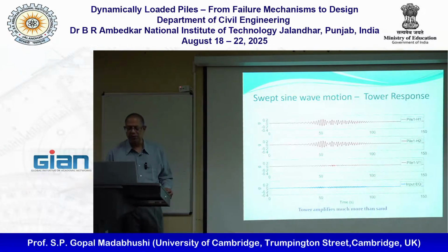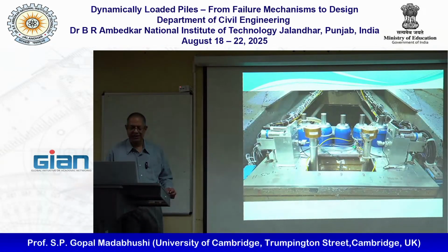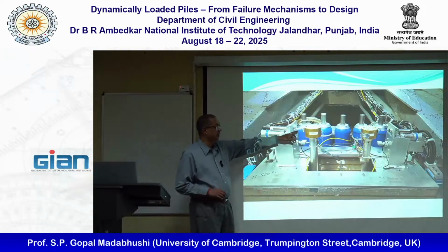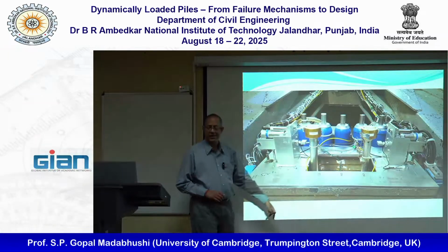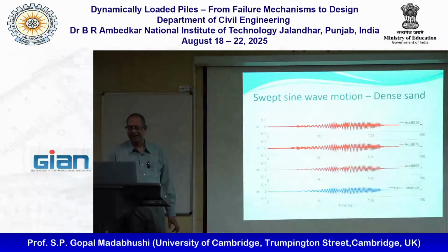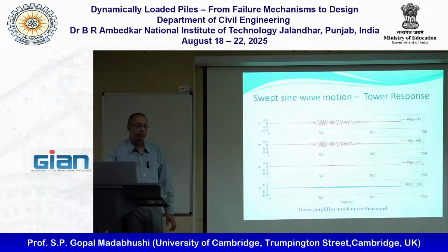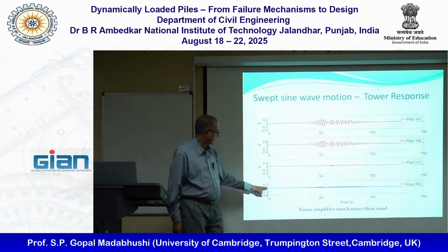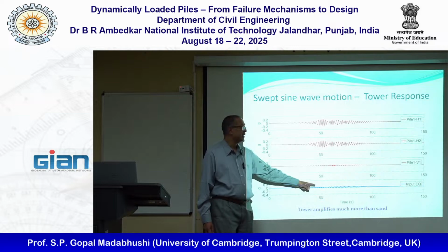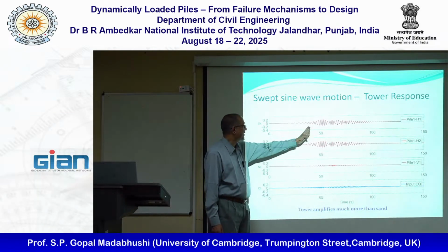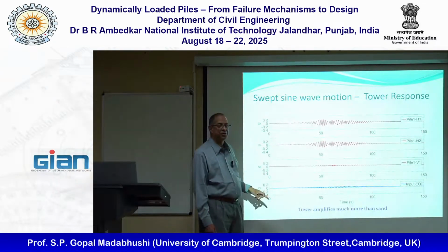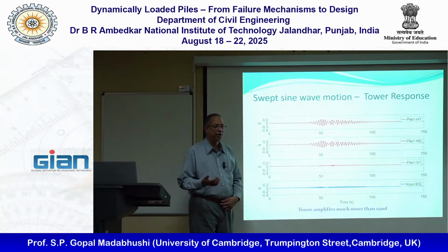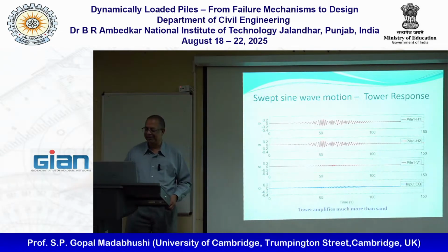In this case, we also had a structure. Basically, it's like a monopile and a lumped mass on the top. So we want to find the natural frequency of the whole thing. So we can get tower response as well. And you can see my input is so small, but the tower is responding at a certain frequency quite strongly. It's almost 0.2 g, and I'm putting in less than 0.05 g, right? So you do pick up the natural frequency quite easily.